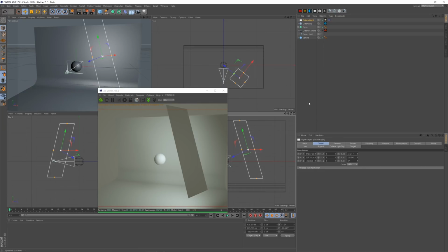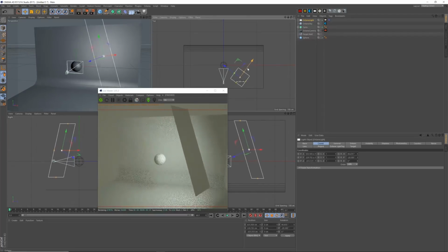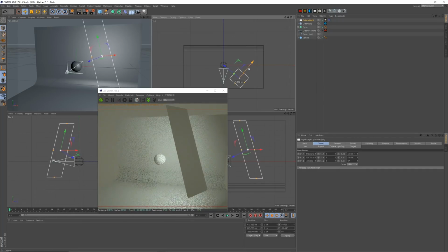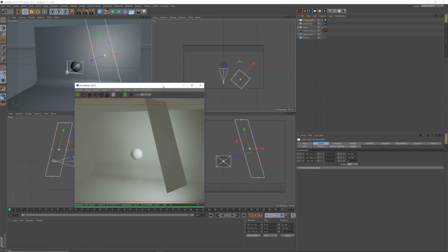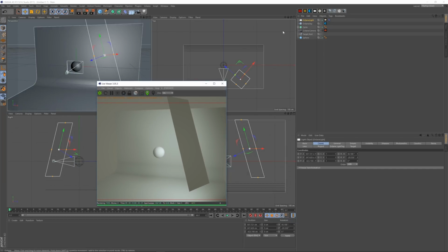Doesn't have to be perfect, but around -20. And if we drag the X axis there, that's around 50. It was already around 50, but somewhere about there. And then drag the Z depth, so we're about at 500. Yeah, so that gives us our first light.